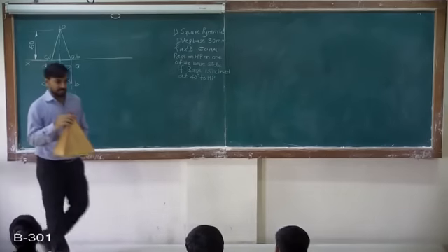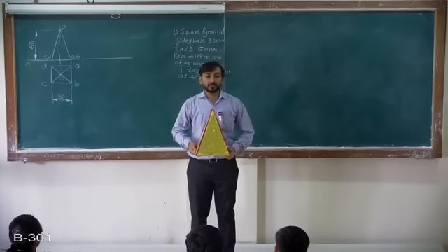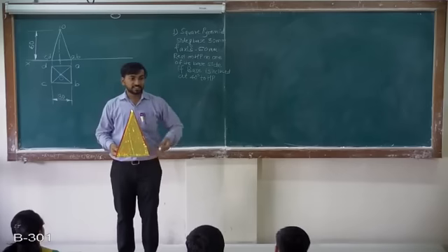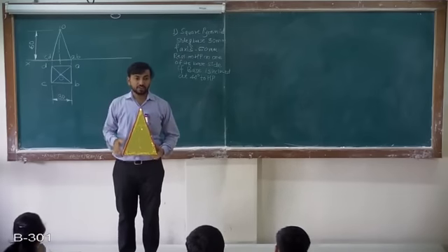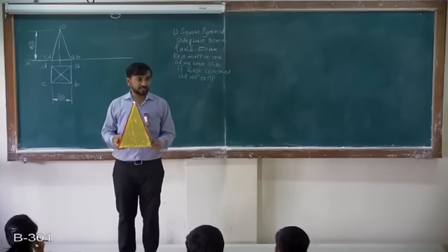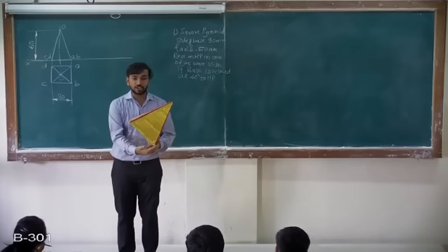So this is the case. Let's say this is the case: a square pyramid resting on HP on its side, axis height was 60. So I had drawn the first stage. In the second stage, it is mentioned that it is resting on this side. I'm going to incline like this, keeping this side always on XY.